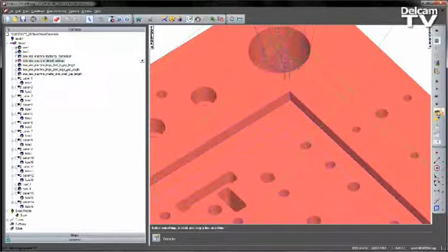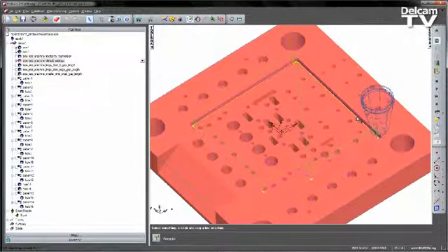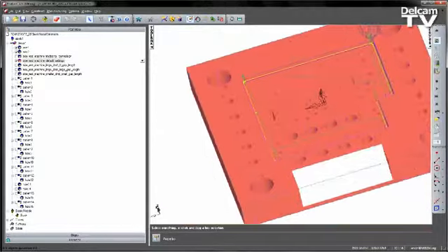So clearing that material away up to this point, I'm just going to remove the rest of the simulation, step the toolpath in, and we can see in this case we are roughing out these corner areas. We'll work our way around the component, using the Alt F3 key to go through these segments. But we can also see that our machining operation is also going around all of these outside faces as well.